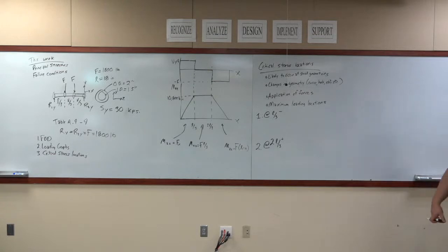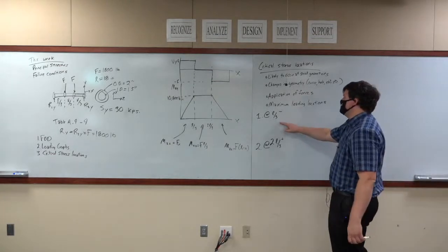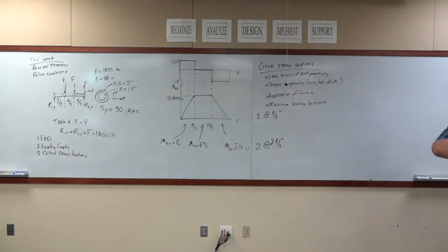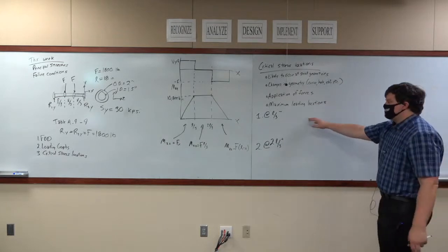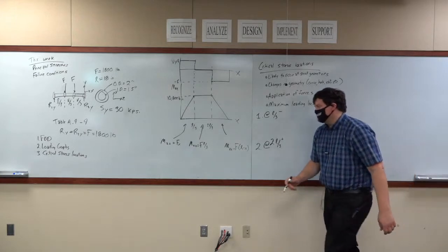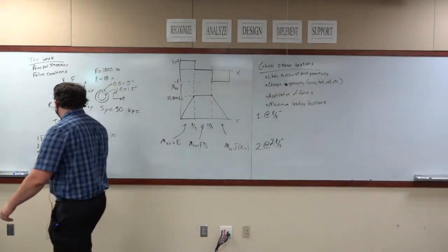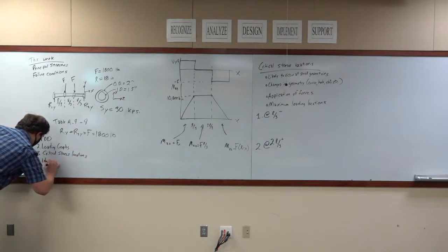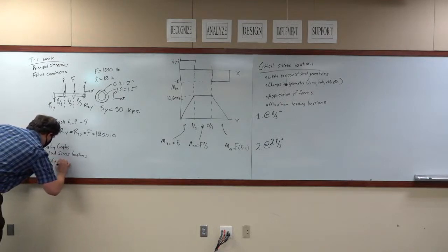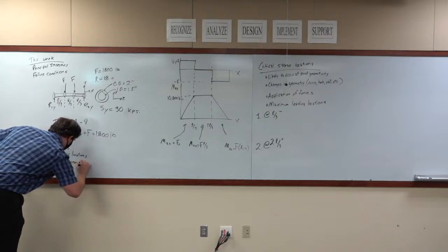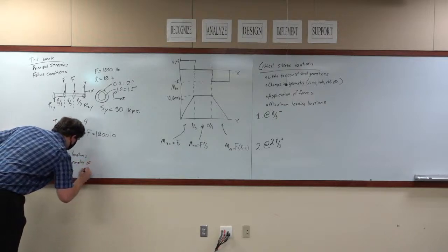Okay? What is the shear force in the y direction? Well, we're going to go ahead and write out what all of our loads are at the critical stress location. Okay? So the next step is, now that we've identified these, identify loads in geometry at critical stress locations.